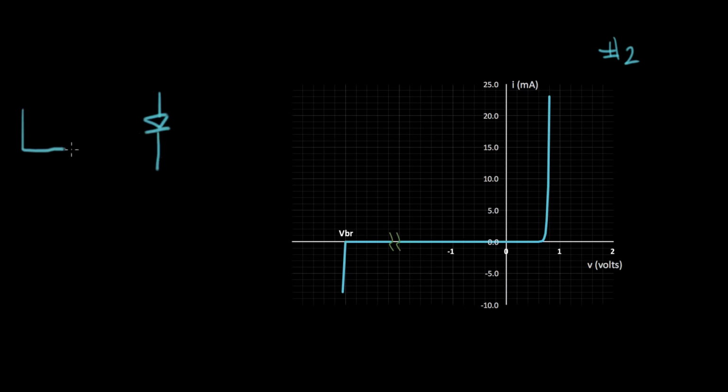So what I would do is I would find some sort of box that made voltage for me, a power supply with an adjustment on it, and then I would also have something that read current. So this is an ammeter, and this is a voltage supply.